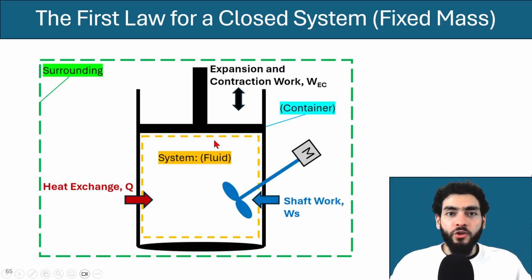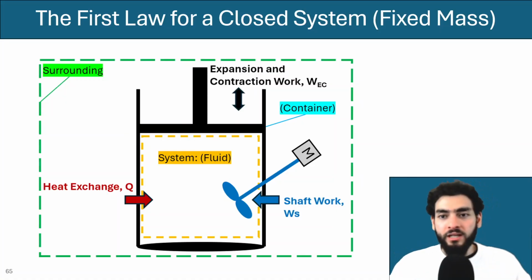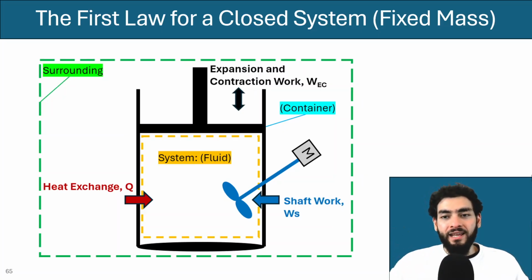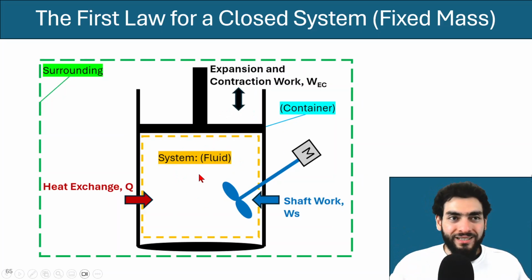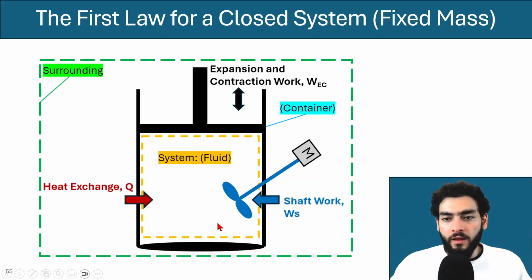the system. Also, if the system was a piston, for instance, then you could apply force by pushing the piston down, and in this case, you are compressing the fluid, and so it's gaining energy. On the other hand, if the fluid itself is pushing against the system up, then the fluid of the system is expanding, and so the fluid of the system is actually performing work against the surroundings. Also, let's say you have a mixing tank of some sort and you have a shaft that's mixing the fluid, then you also have shaft work that's being applied into the system.